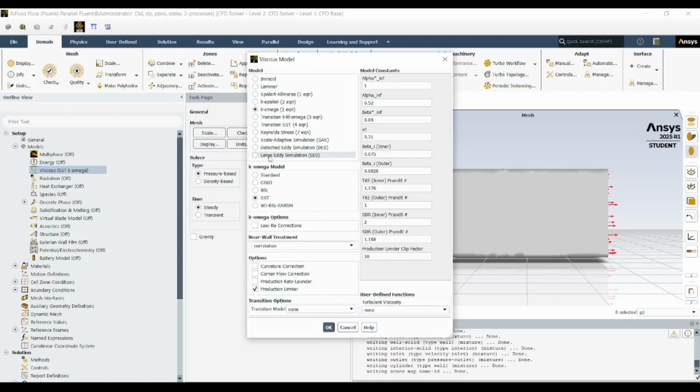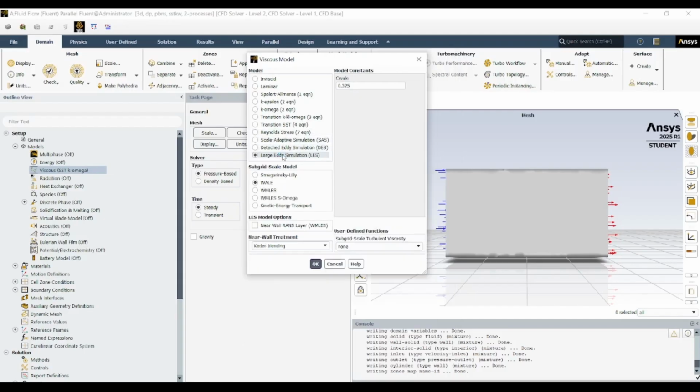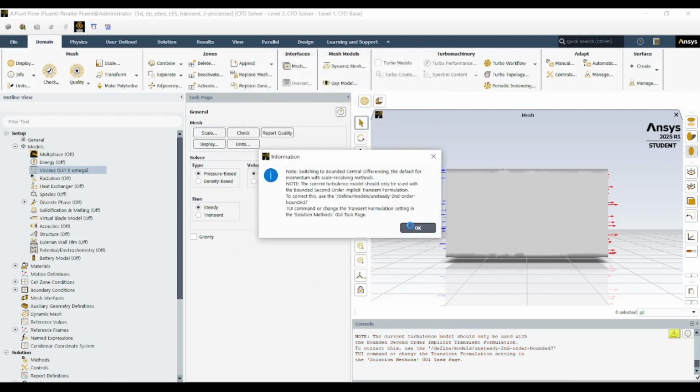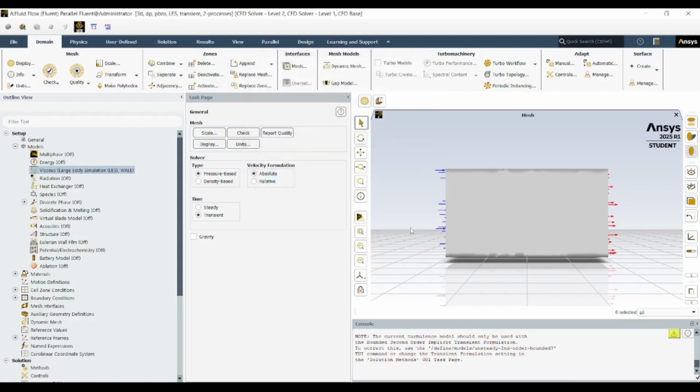Another valuable post-processing step is examining drag decomposition into pressure drag and viscous drag. Fluent allows you to separate these components, showing that for bluff bodies like a cylinder, pressure drag, or form drag, dominates due to flow separation. By refining the mesh or introducing turbulence models that delay separation, you can observe how the total drag reduces, demonstrating how aerodynamic shaping affects performance.